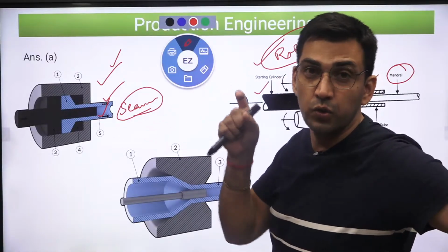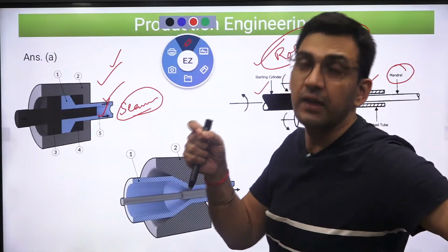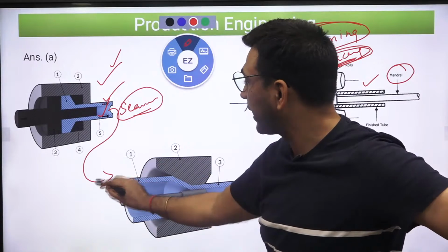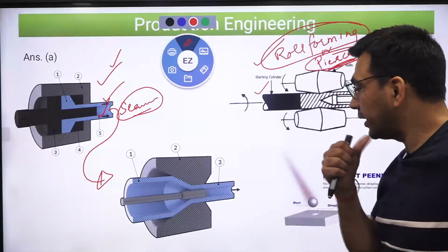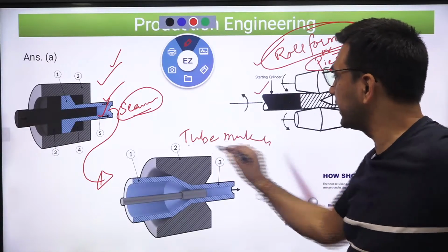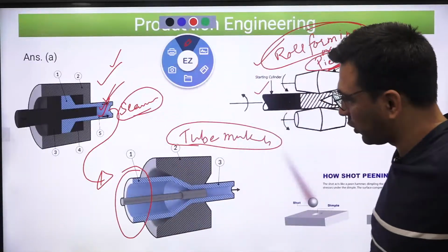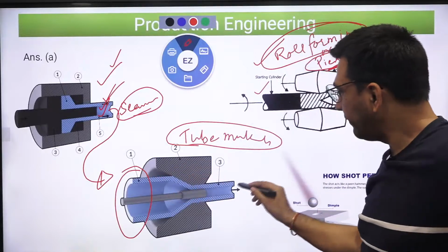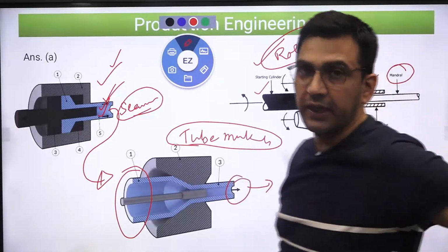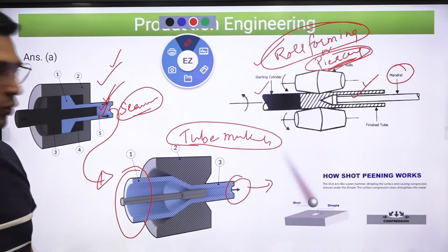At the same time, it doesn't have a very high strength. So if you want to use the pipes or tubes in an application that demands very high strength as well as very good dimensional accuracy, then you can deform that particular pipe. Again, we call it a tube making process. Basically this is a cold forming process where the already formed tube, from this process or this process, is further pulled through a die in a cold working operation. And since you are deforming it or pulling it in the cold working process, obviously strength will be increased and dimensional accuracy you can also obtain over here.